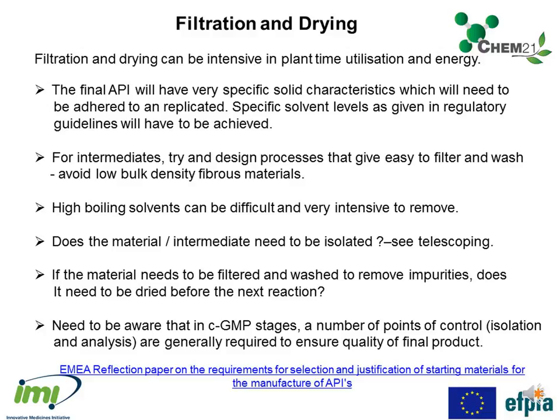Generally for intermediates, we need to try and design processes and crystallizations that give easy to filter and wash materials. So that's avoiding low bulk density fibrous materials. High boiling solvents, as we mentioned earlier, these can be difficult and very intensive to remove. So a high energy requirement in distillation and high energy requirements in drying.